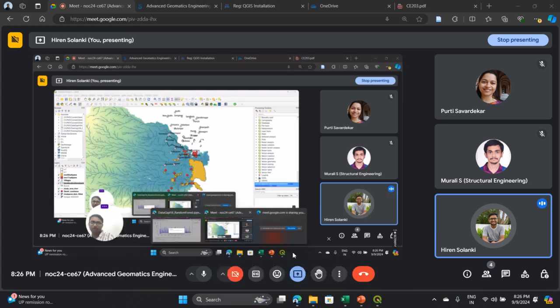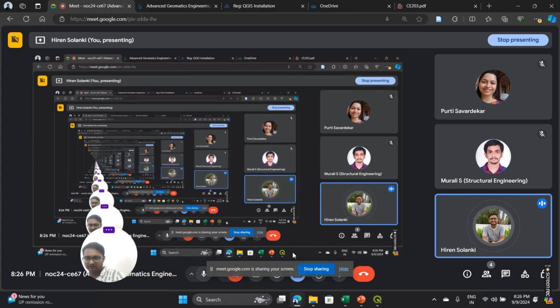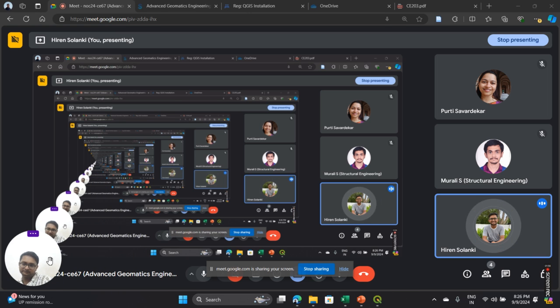What you can do is search different news articles and see what kind of applications or problems there are in your area and how you can solve those problems using geospatial data. So the first target is to identify the problem. Then you have to see what kind of data will be relevant for this application, which raster data and which vector data is necessary for solving the problem. And once you know it can be solved, download and collect all the data sets. If it is not available, generate it using a CSV file from a newspaper article, some books, a forest area report or a wildlife report.